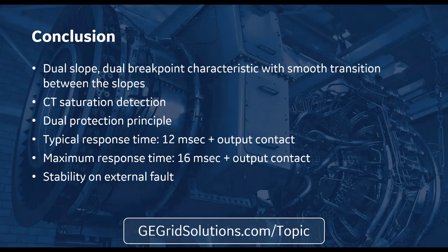Can potential currents in the shield wire of a cable affect this scheme? I don't think so. When we're talking about high levels of fault current, our fault currents will be much above whatever capacitive discharge or EMF interference we see in any type of unshielded cable. And most of the time CT cables are unshielded.